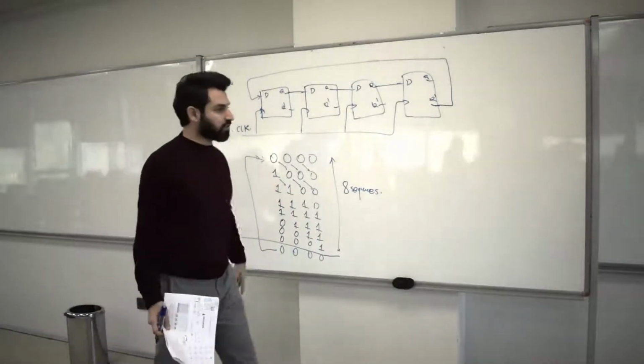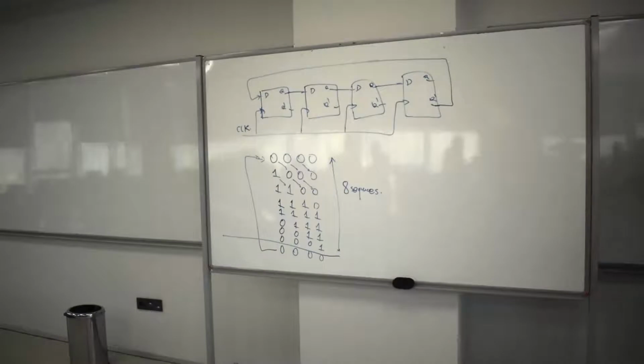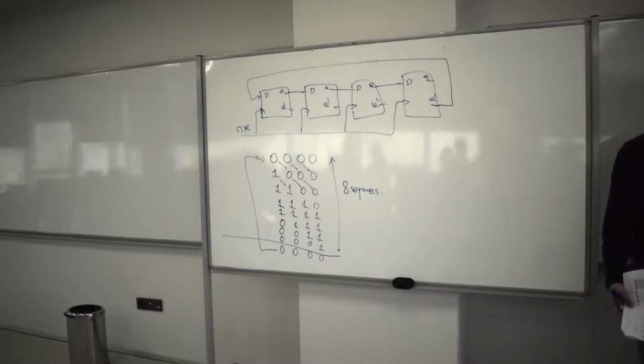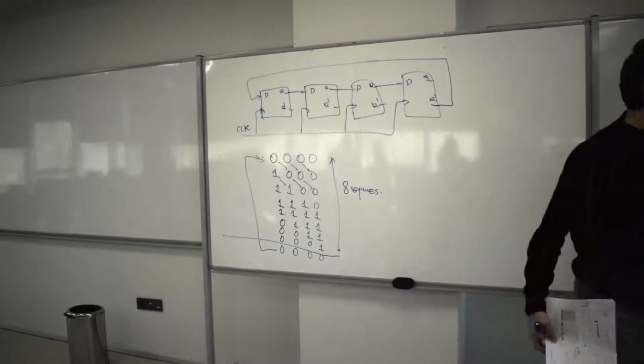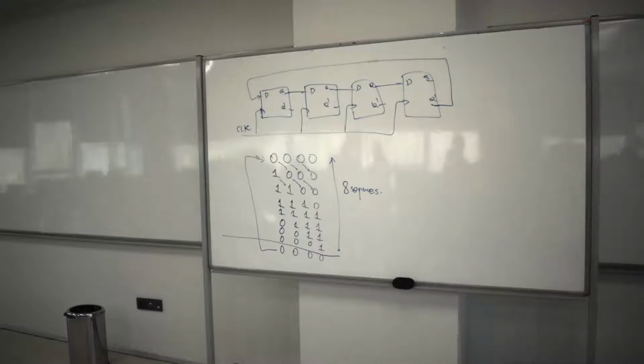But those sequences do not look like the format that I have here. The format that I described earlier was that in each bit position, there is only one 1, logical 1. The rest of them are 0. That's the format that I defined because in that particular way, I can enable modules 1 at a time.